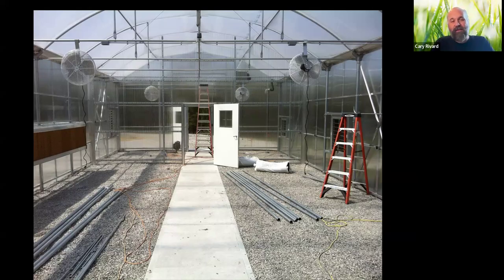I work with a lot of school gardens and school greenhouses. They don't have the ability to replace the roof, right? So for them, it's going to be better to have a rigid roof because it's a lot lower maintenance in the long term. But that being said, if you do have a problem with twin wall polycarb up here, think about how difficult it's going to be to get there and fix that problem, fix that leak. Whereas with polyfilm, if something happens, it rips, or a hailstorm, you just put a new piece on.